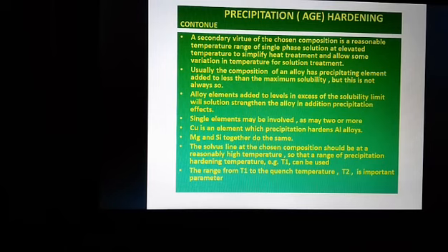Single elements may be involved, as may two or more. Copper is an element which precipitation hardens aluminum alloys. Magnesium and silicon together do the same.